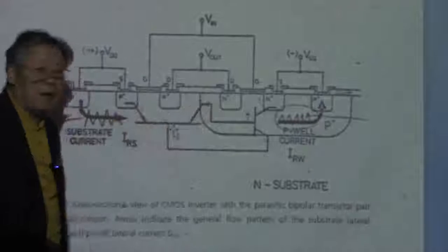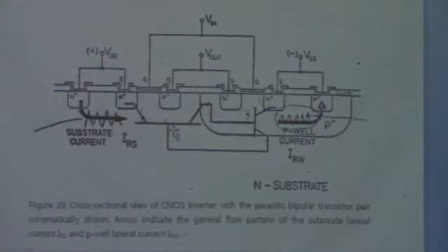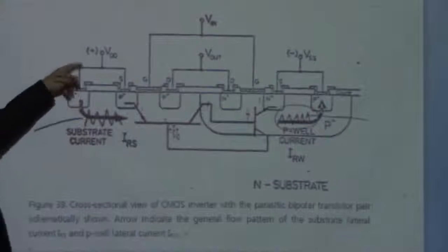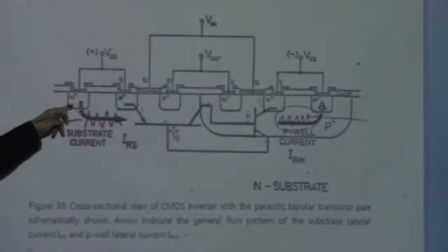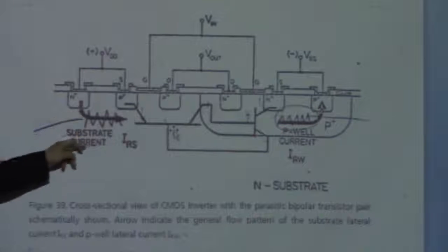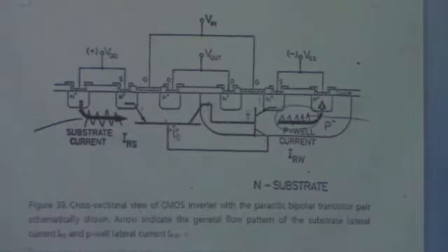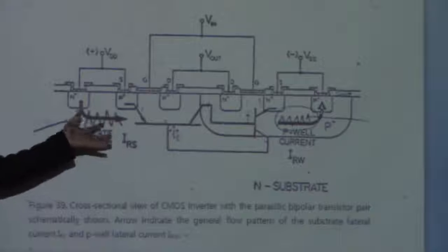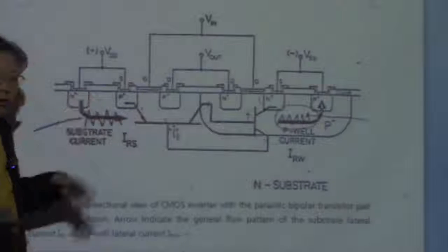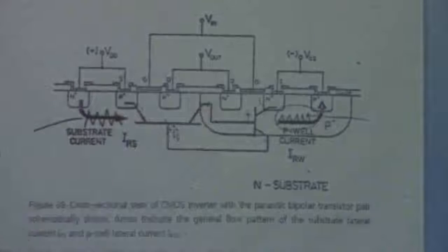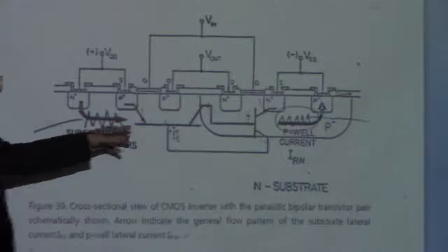That is a kind of bipolar transistor. So if this bipolar transistor is going to be triggered by the applied voltage, the VDD, on this N plus, then it is going to have a current, I sub Rs, and this current is going to be hugely accelerated through this bipolar transistor by the value beta, the gain of the bipolar transistor.